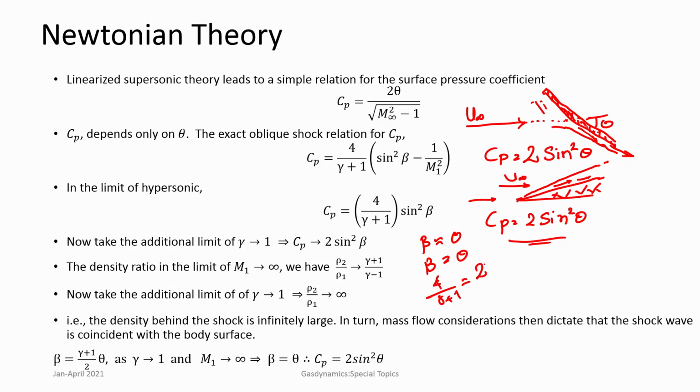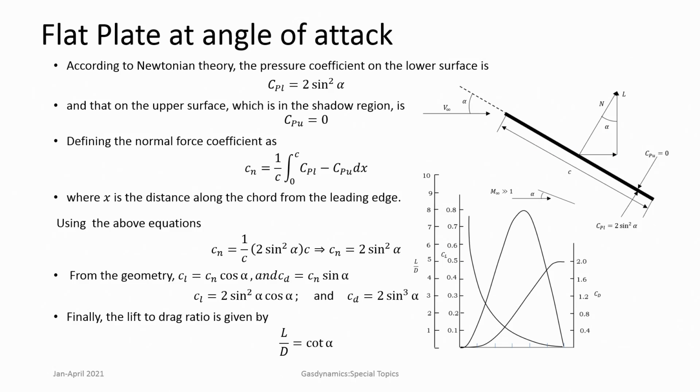So, even if we consider a thin shock layer, we are able to see that whatever Newton was predicting in hypersonic flows in the limit of large Mach numbers, we are very close to it. So, Newtonian methods to quickly estimate the aerodynamic forces is used effectively in hypersonic flows. It is an estimate to start with, and later more refined theories can be used.